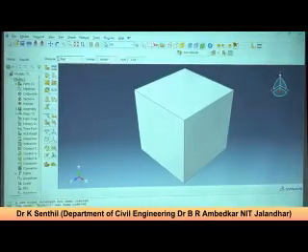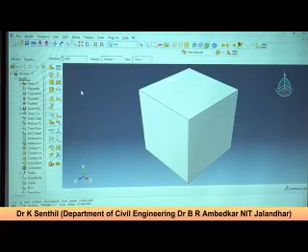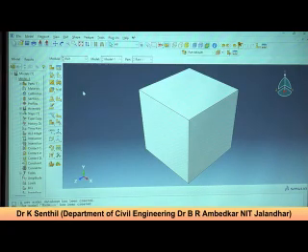So now there is a pile. See, basically when we model the concrete, we don't model it like a reinforcement and a concrete. We have the option to embed the reinforcement within the concrete, because it is tightly connected, whereas in the soil it's not like that. We cannot just embed into this element, so we have to do cutting. So for the pile, it's like a borehole, right? We have to make a borehole. So how to do this borehole?